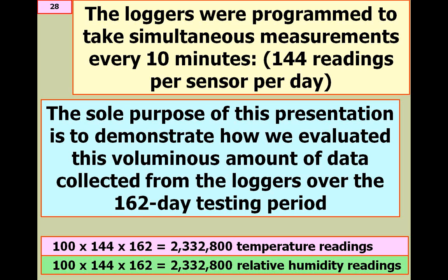player. And this would be no different than say a normal practice that a firm like ours would do, which would be to take a pin-style moisture meter and go to wood or OSB plywood sheathing at a wall and measure the moisture content ratio of the plywood sheathing, and perhaps at one location we find that it's 18%, and at another location we find that it's 24%.